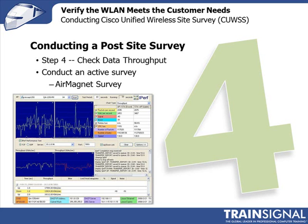So it records the data rate in both directions. And that's what's being shown here on this slide. You can see the iPerf results, the downlink traffic and the uplink traffic, where the downlink is from the access point to the client and the uplink is from the client to the access point.